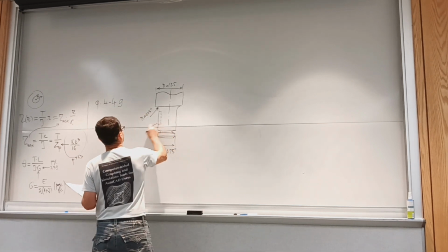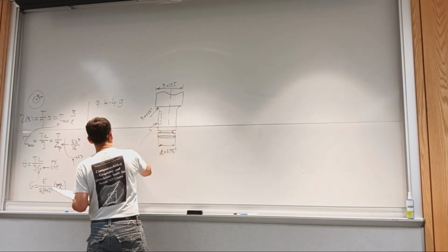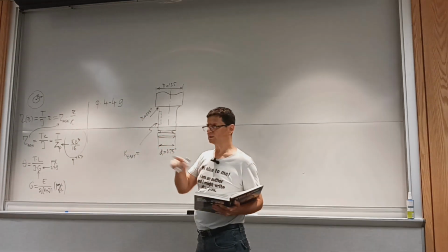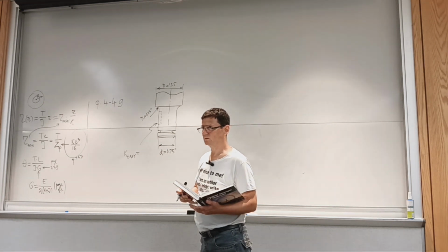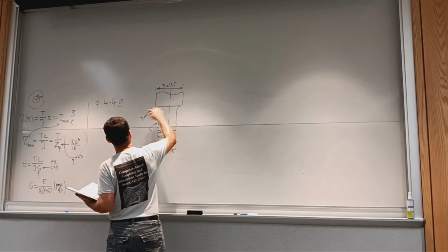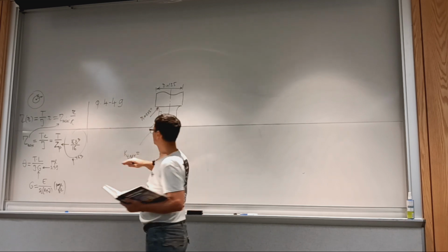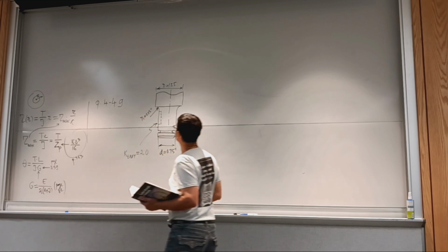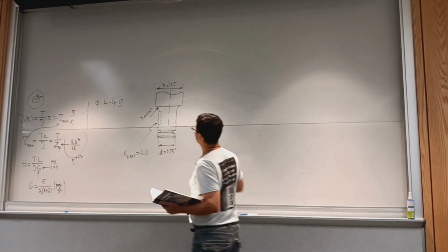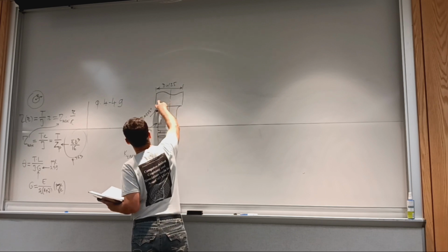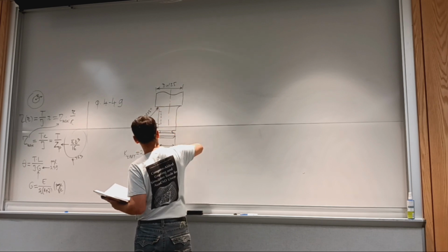Okay, so we can tell right away the stress concentration factor at the key for torsion. It's in the book, I think elsewhere also in the book, in the chapter. So for profile key set, it ends abruptly, not the sled runner. For sled runner it's 1.6, this is 2.0, okay? And we're going to also look up the stress concentration factor in torsion for a step shaft with a fillet radius, assuming these two diameters.